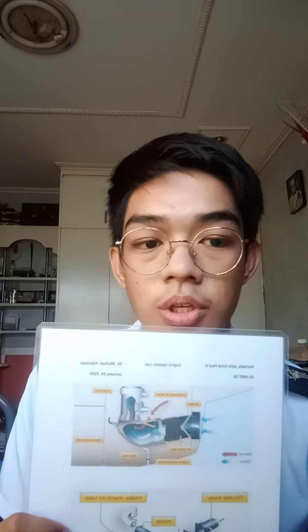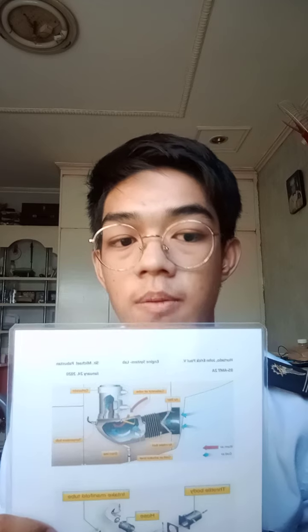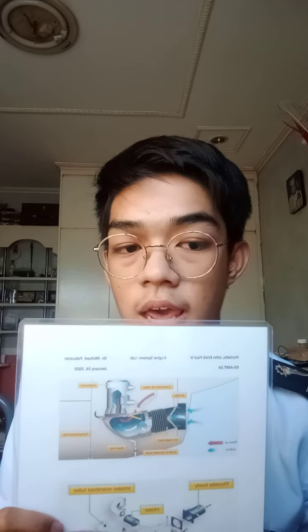Carburetor icing occurs when the temperature is lowered in the throat of the carburetor and enough moisture is present to freeze and block the flow of air to the engine. The carburetor heat valve admits air from the outside air scoop for normal operation, and it admits air from the compartment for operation during icing conditions.